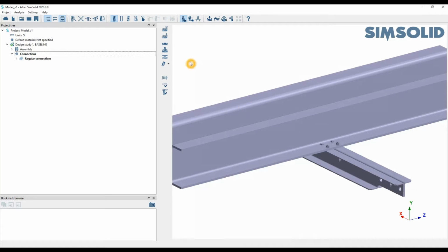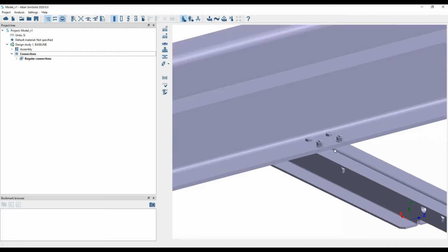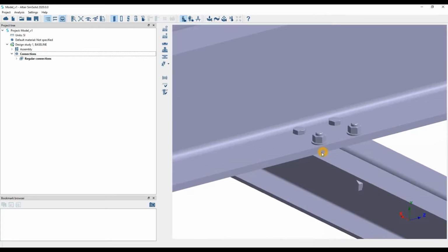But obviously we already have all of our connections established here, so I don't need to go through and do all of that again. If you want to incorporate any sort of welds, you can create spot welds, seam welds within SimSolid. You can also create adhesive connections from the solids itself, so if you already have your adhesives drawn up, you can specify different solids being adhesives.